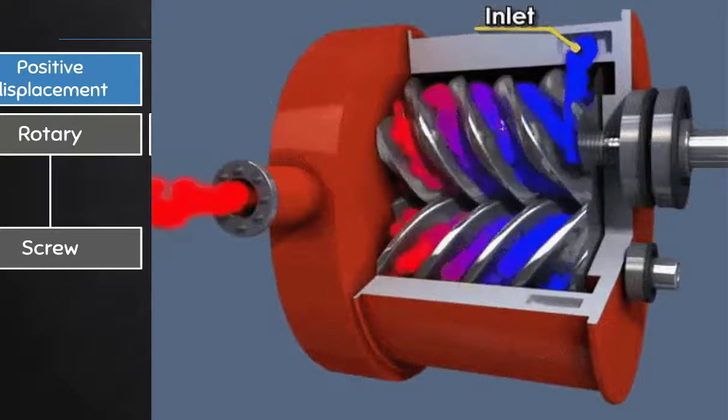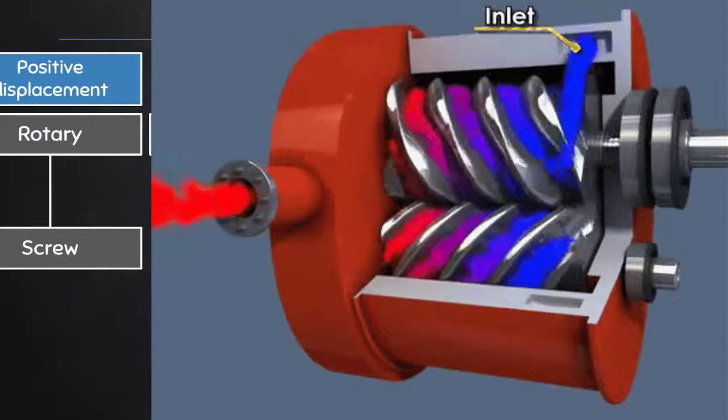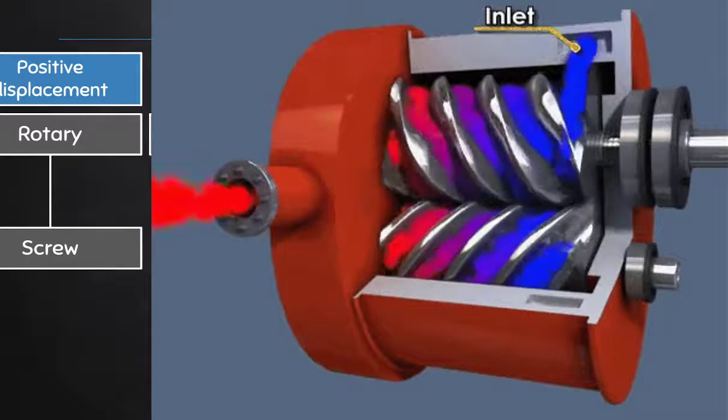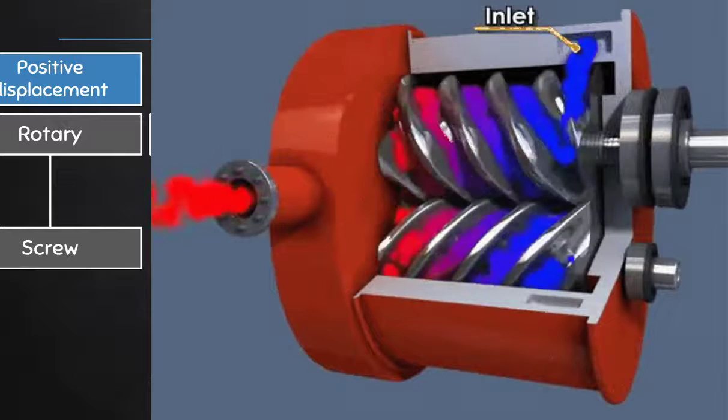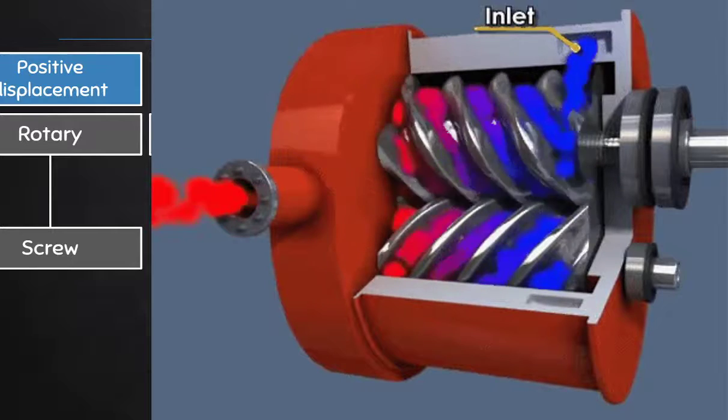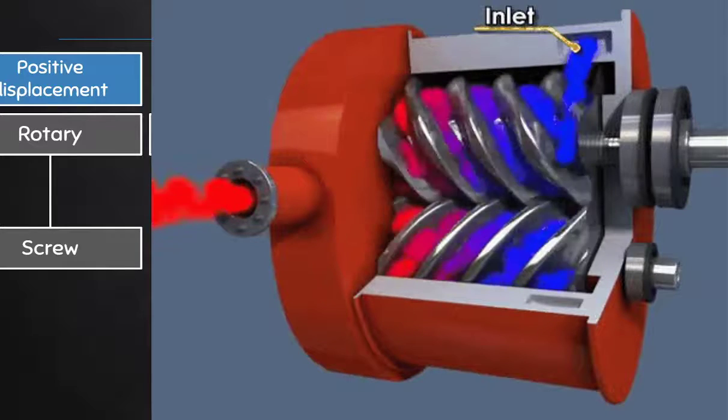These types of fluid movers are most useful for things like polymer melts, where you would not only move the polymer melt along, but you could also increase the temperature of the fluid in question by changing the way the vanes or the screws are set. So you can also use this for mixing and extruding applications, where you need to mix dyes into the polymer before you extrude them out into a die.